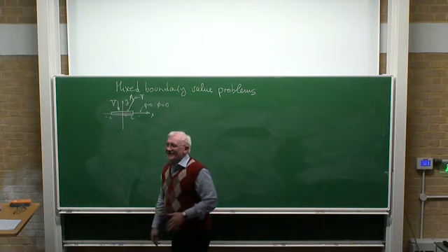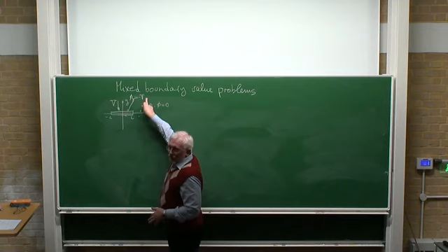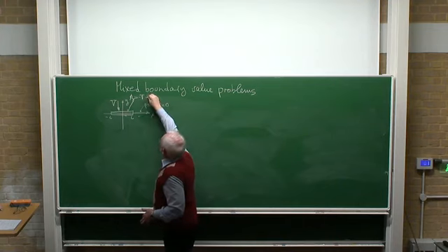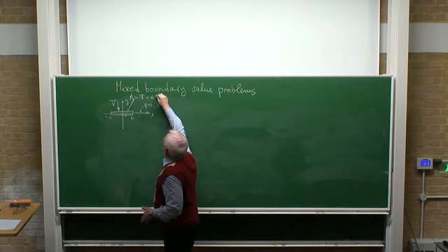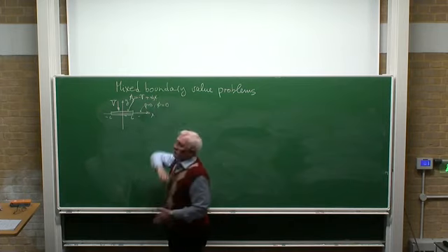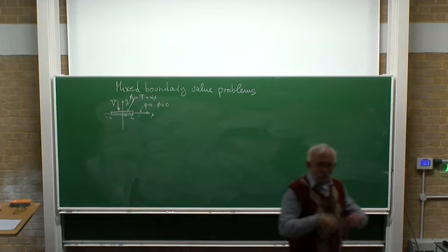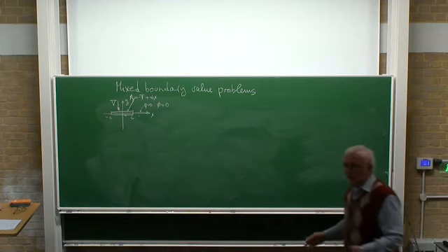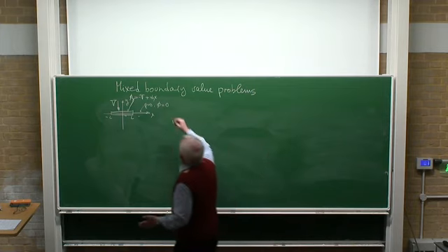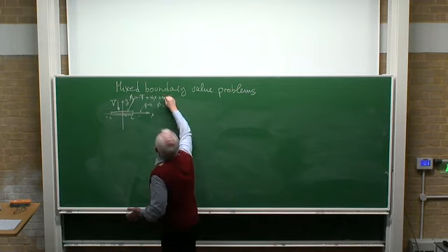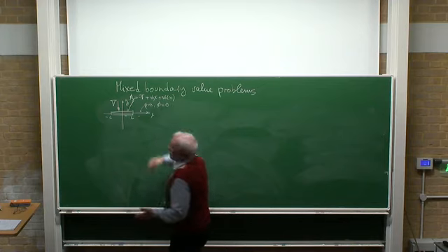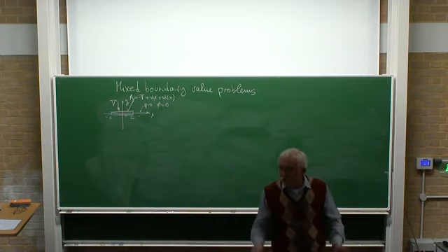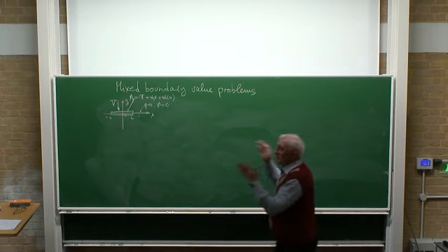If the plate in addition rotates, this boundary condition becomes more complicated. There should be plus alpha x if it's rotated. If it's flexible, so it can be deformed, then it will be w of x, the deflection caused by impact. So it's an instant problem.